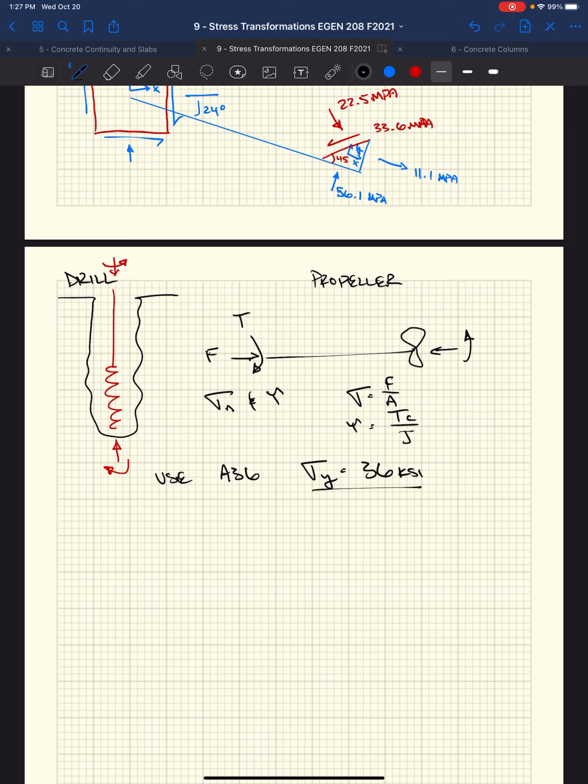Okay. Yield stress for A36 steel, which is called mild steel. It's what a lot of plate steel is made out of, typically channels, angles. If you go to Pacific Midwest and you got something that's made out of those components, most of it is made out of A36 steel. Very common. It has a yield, but as we talked about with our tensile test, there's an ultimate capacity as well. The ultimate stress for A36 steel typically hovers around 58 KSI.